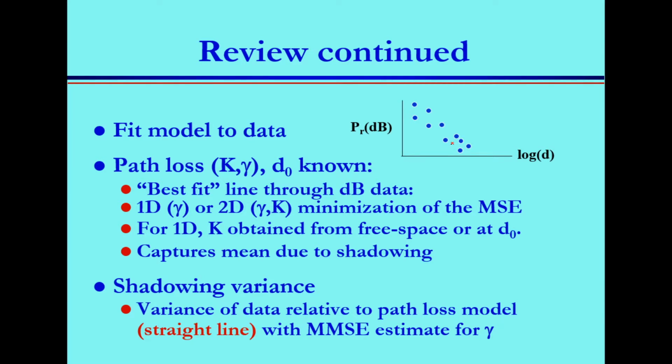After you record these measurements, you go to the lab, you open MATLAB or any software in which you can use fitting and modeling methods, and you plot these points, the received power versus the distance. You say that at distance equal to 100 meters, the received power was, for example, minus 80 dB.